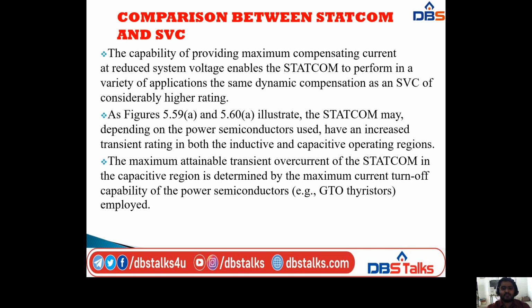Next, the capability of providing maximum compensating current at reduced system voltage enables the STATCOM to perform, in a variety of applications, the same dynamic compensation as an SVC of considerably higher rating. So here I will show the diagrams.